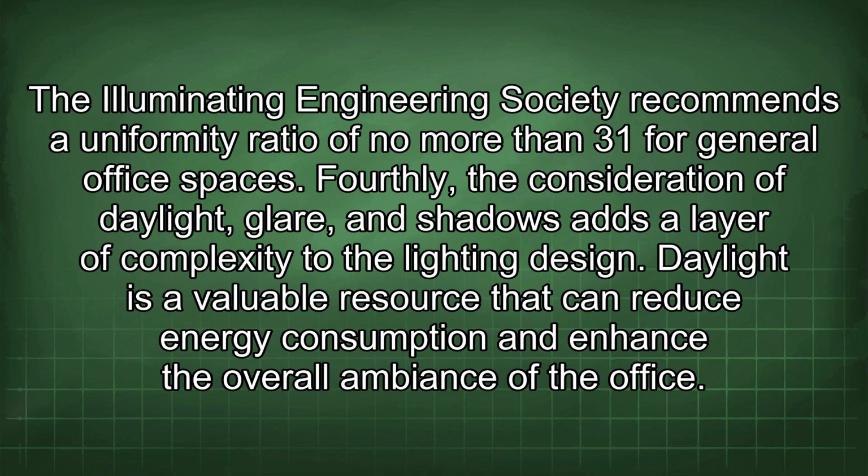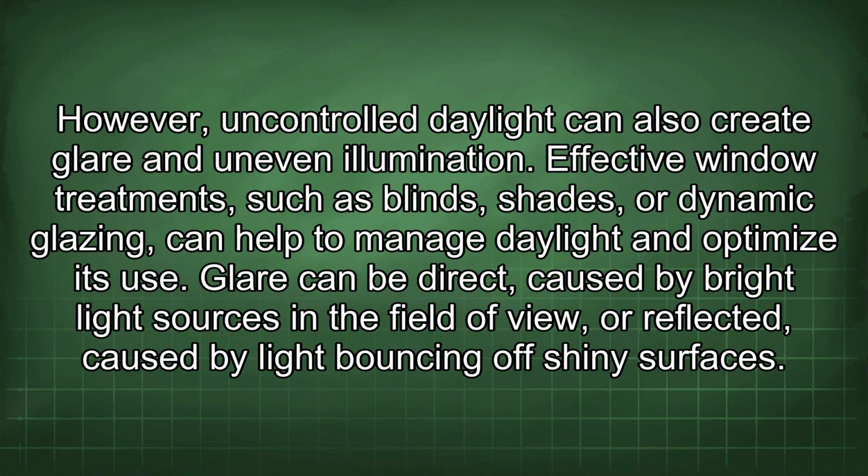Fourthly, the consideration of daylight, glare, and shadows adds a layer of complexity to the lighting design. Daylight is a valuable resource that can reduce energy consumption and enhance the overall ambience of the office. However, uncontrolled daylight can also create glare and uneven illumination. Effective window treatments, such as blinds, shades, or dynamic glazing, can help to manage daylight and optimize its use.